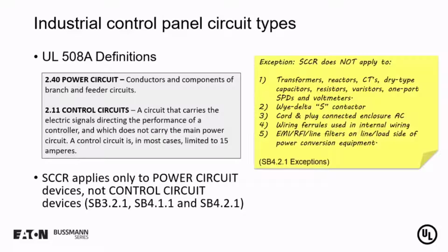Thanks, John. And again, I'd like to add the importance of having the proper SCCR when it comes to either industrial control panels and industrial machinery. Many of our attendees, I'm sure, have seen equipment that comes with a label of 5 kA or 5,000 amp rated SCCR. And I think what your users will find is that quite simply 5 kA is not adequate for most commercial and industrial installations. And that's why we're doing this webcast, to really explain to our users here what can be done to get equipment that is rated properly for their available fault current at their system.